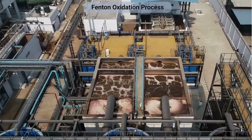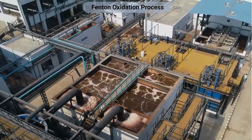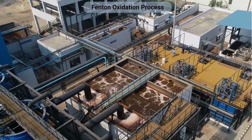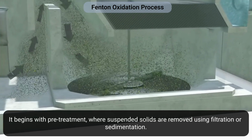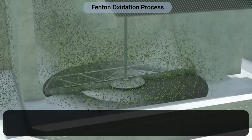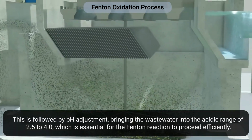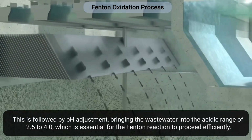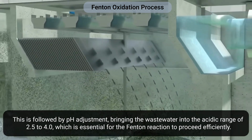The Fenton oxidation process for textile wastewater treatment involves a sequence of well-defined steps to ensure effective removal of dyes and organic pollutants. It begins with pre-treatment, where suspended solids are removed using filtration or sedimentation. This is followed by pH adjustment, bringing the wastewater into the acidic range of 2.5 to 4.0, which is essential for the Fenton reaction to proceed efficiently.